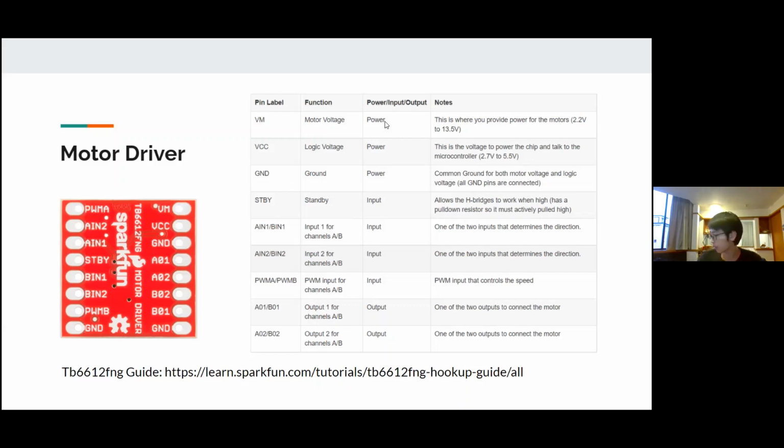That is where your battery supply comes into play. So it requires a power of 2.2 volts to 13.5 volts. We are using 4 AA batteries in the battery case, which is in series, 6 volts to supply power. And VCC is the logic voltage.